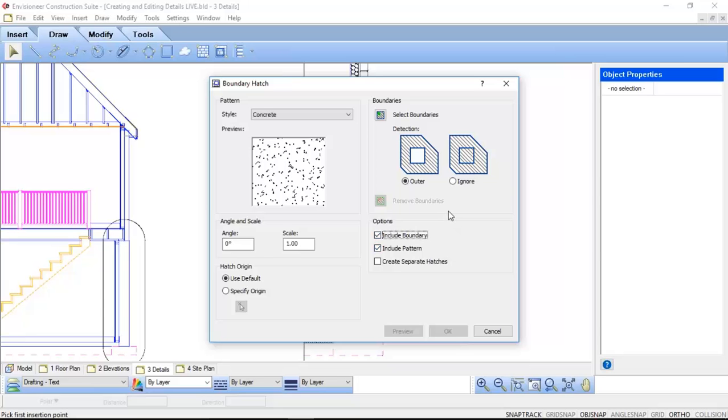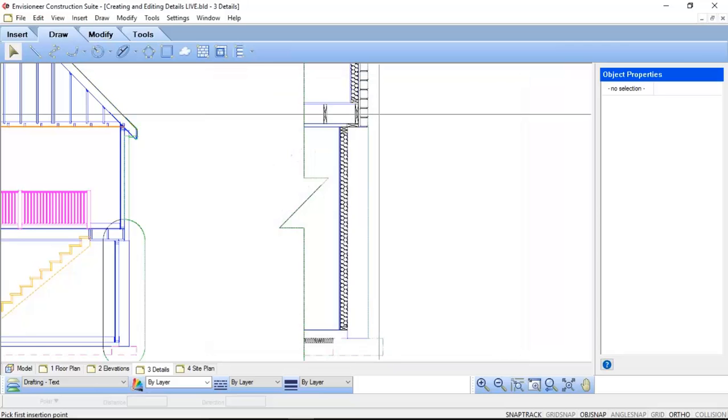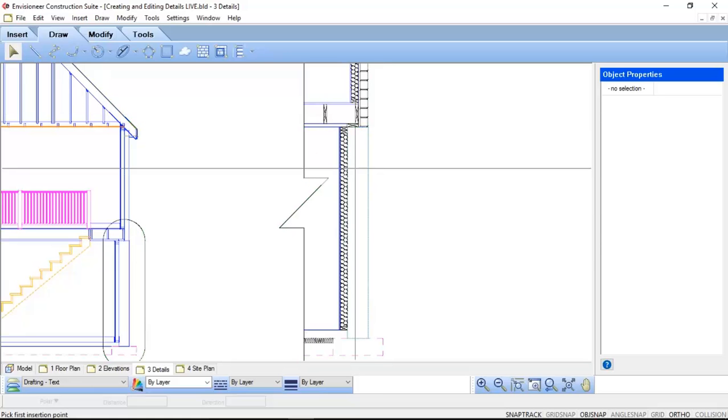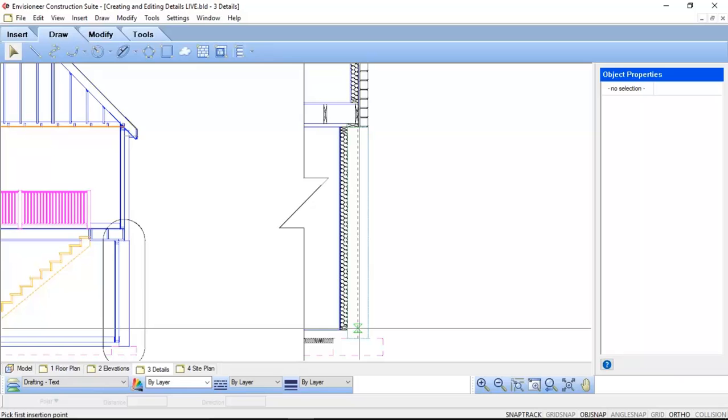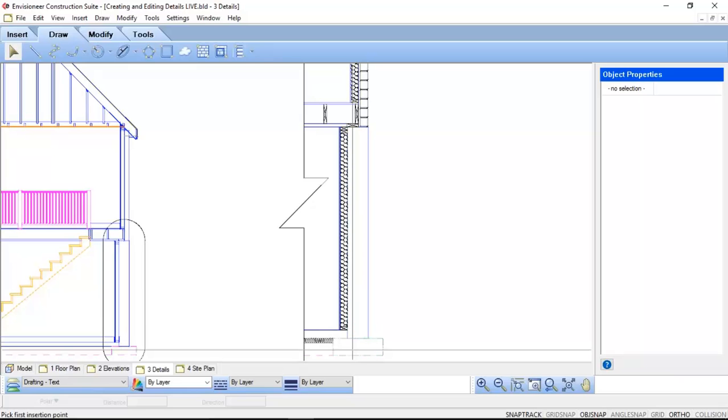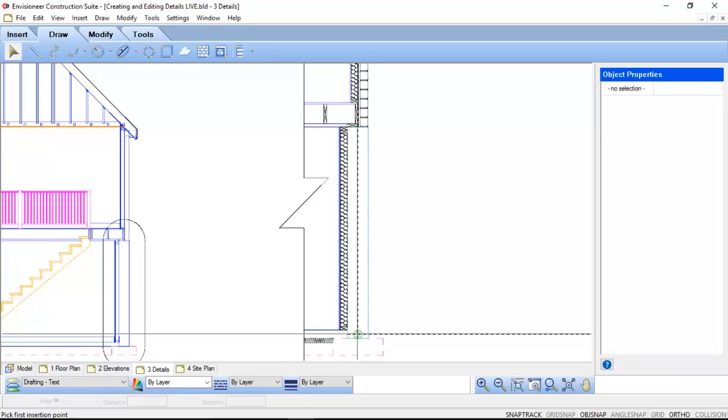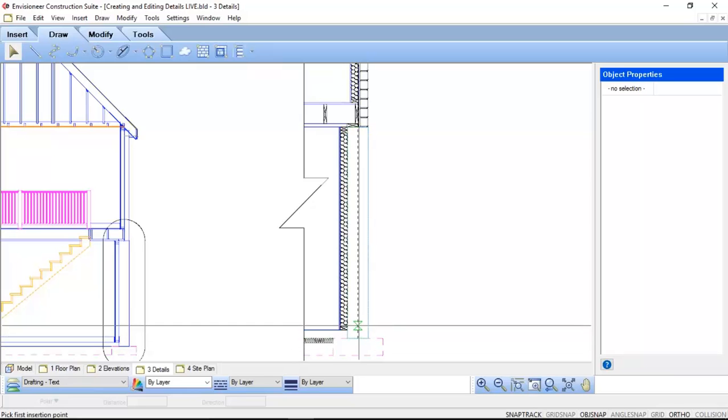And then, of course, what I need to do now is to select my boundaries. So I need to click on this button in the upper right corner. You can see as I move my cursor around, it's going to create a dotted field around the edge of any definable contained area that has an identifiable perimeter.